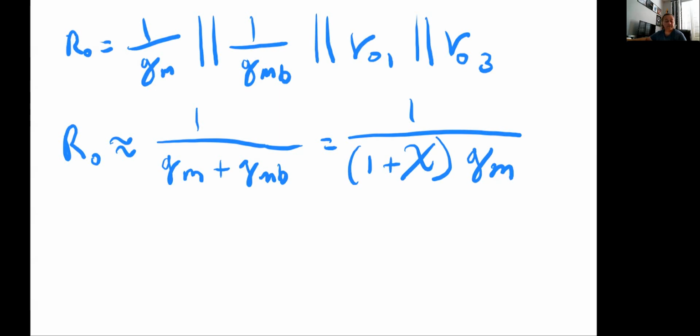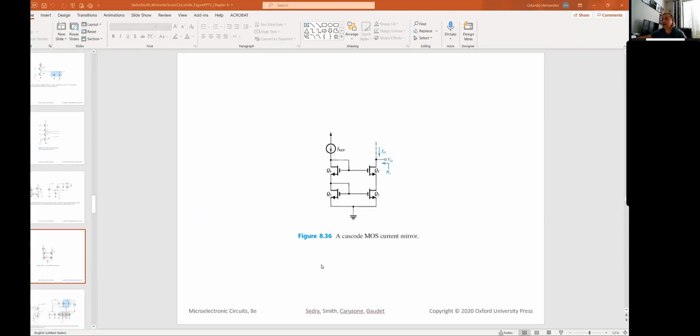For example, a couple of notable things are what is called the cascode current mirror. Basically, this is applying the same cascoding principle to the current mirror that we started with. If it was good for the amplifier, why not for the current mirror, right? That gives you a higher output resistance, as seen at the node VO, where you're providing the bias, if you're using this to provide a bias or a load.